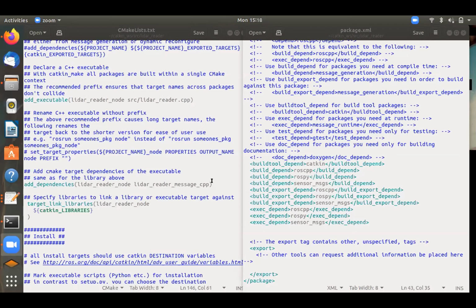And if the topics from the simulation are being published, MATLAB will read them. It's the same as if you wrote this package now and launched it separately. It's just a different module. Your simulation will be publishing laser scans continuously, and at the moment you start your MATLAB script, it can subscribe to that topic and listen to the information. Then you can do all the processing in MATLAB, and just like you subscribe to a topic, you can publish some sort of message back to your simulation, and it will execute it.